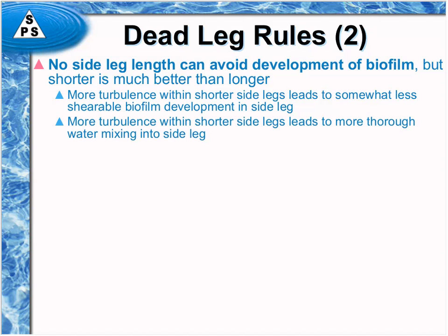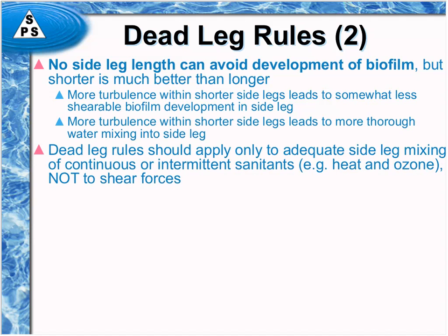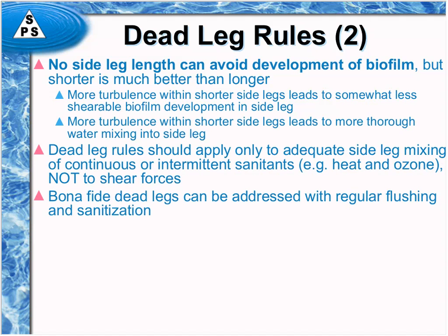But actually, most of the effect of the dead leg is really to allow the mixing of sanitizing conditions down into that side leg, much akin to the original purpose with the milk industry. It is not related to shear forces. That's been the unfortunate phenomenon that has been claimed to be the benefit of shorter side legs, and it really doesn't have much impact.